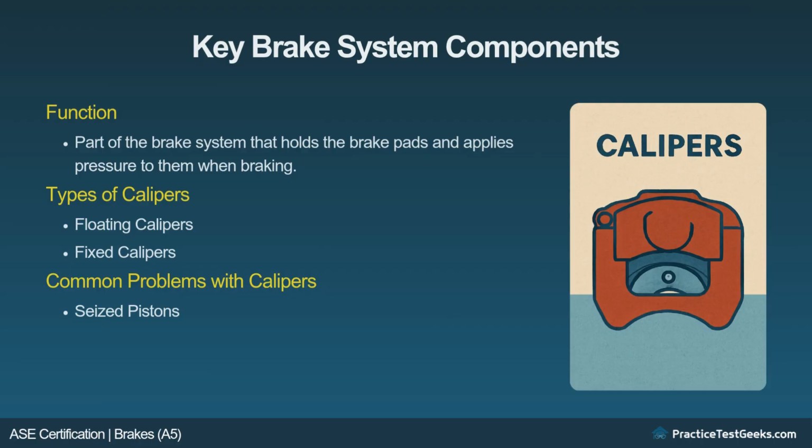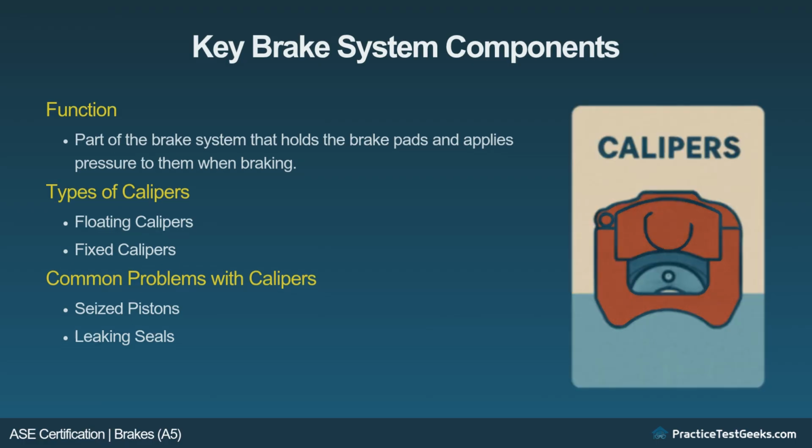Common problems with calipers. Seized pistons. Caliper pistons can seize up, preventing the brake pads from properly contacting the rotor. Leaking seals. Leaking seals can cause a loss of brake fluid, leading to decreased braking performance.